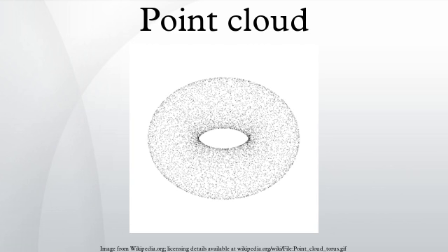Some approaches, like Delaunay triangulation, alpha shapes, and ball pivoting, build a network of triangles over the existing vertices of the point cloud, while other approaches convert the point cloud into a volumetric distance field and reconstruct the implicit surface so defined through a marching cubes algorithm.